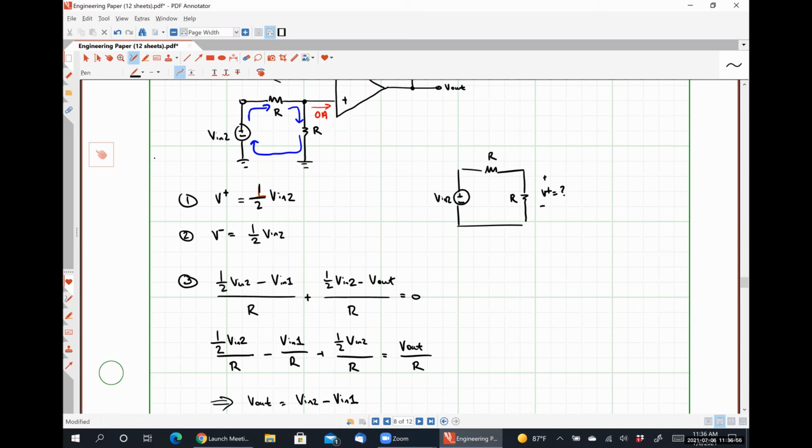I would argue that it is not entirely necessary for you guys in particular to memorize the equations for an inverting op amp versus a non-inverting op amp versus a differencer or anything like that. But you can absolutely use these circuits to not have to go through the 3-step analysis process. So if you recognize it, then you can use that result. But there is nothing at all wrong with you going through that 3-step process for everything.